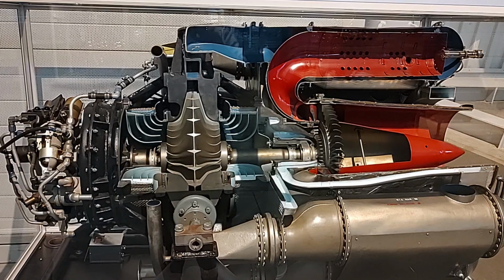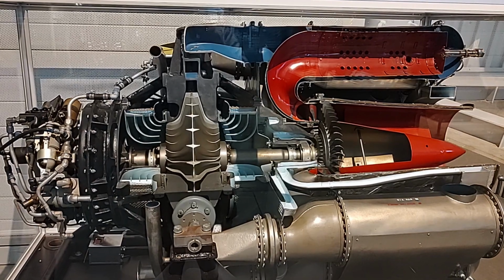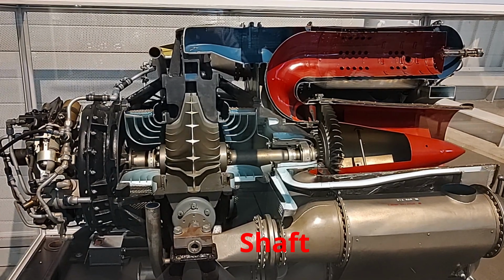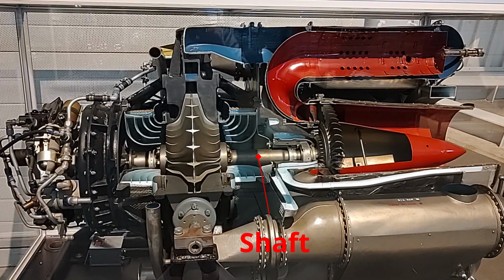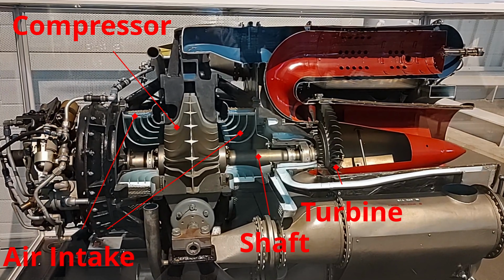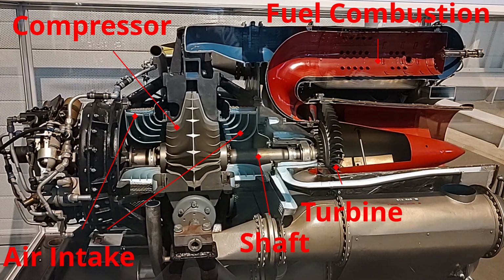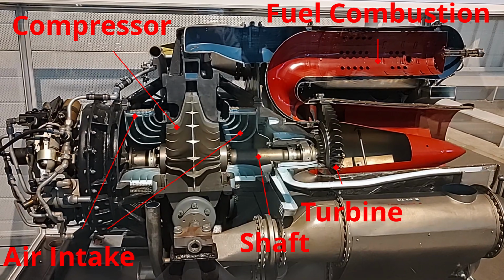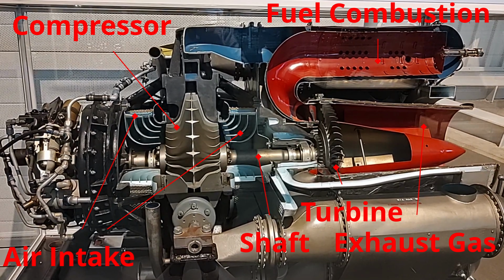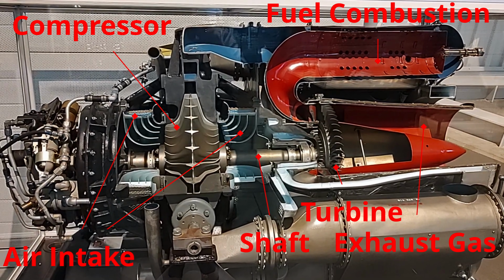This engine had a single shaft, a single compressor and turbine disc, and utilized a reverse flow combustion chamber. What are these components? Simply put, a rotating shaft runs through the engine and links the compressor and turbine together. The compressor draws in and compresses incoming air. Fuel is then injected into the pressurized air and ignited. The turbine extracts energy from this process, which in turn drives the compressor. The remaining exhaust gas is blown out the rear to create thrust. Check out my video on how jet engines work for more detail on this.